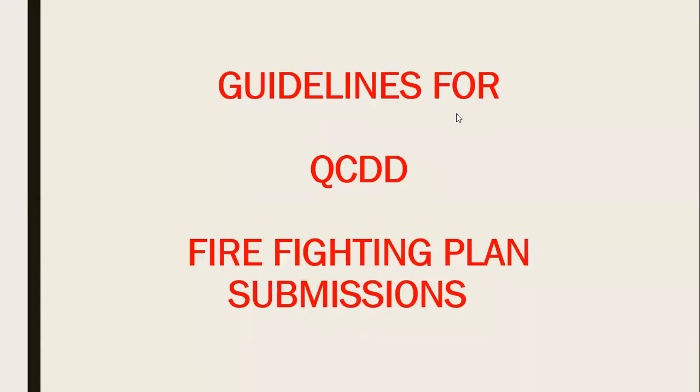Here it is. This is the guidelines for QCDD for the firefighting plans submission. For you, as a mechanical part, you have to submit 2 sets of drawings. First one related to the firefighting, second one related to the smoke management, which we call the air conditioned mechanical ventilation system, ACMV. So 2 sets of submissions will be required.